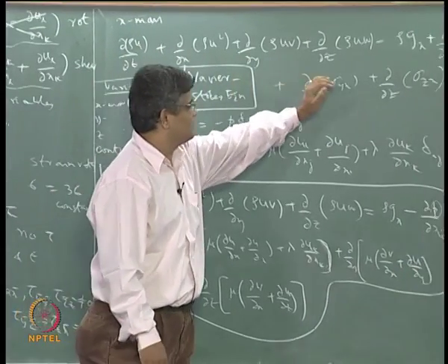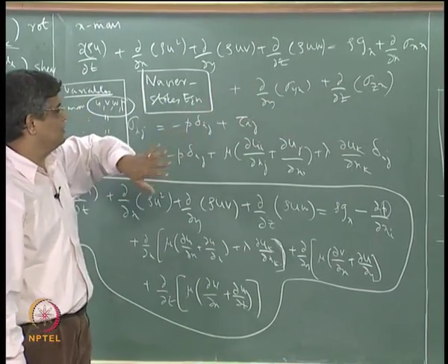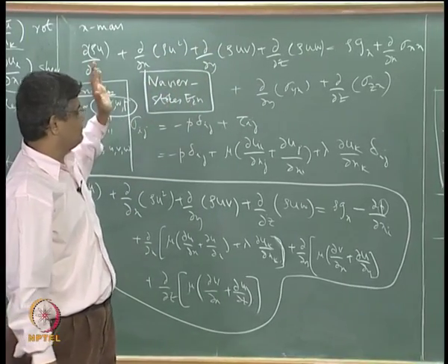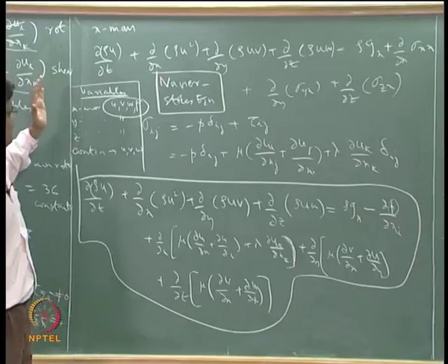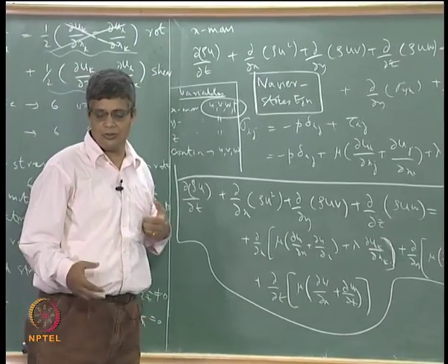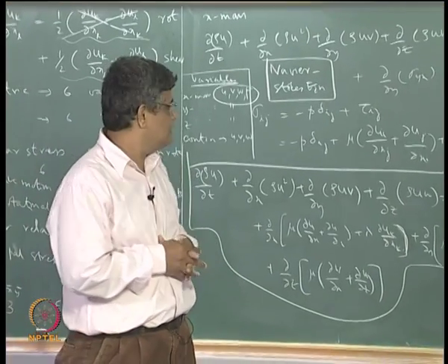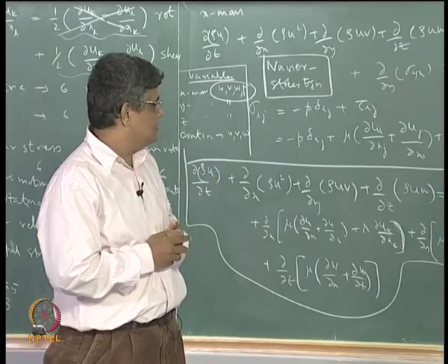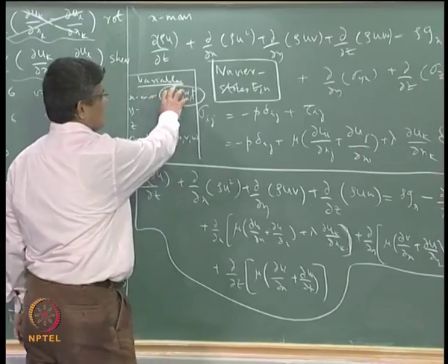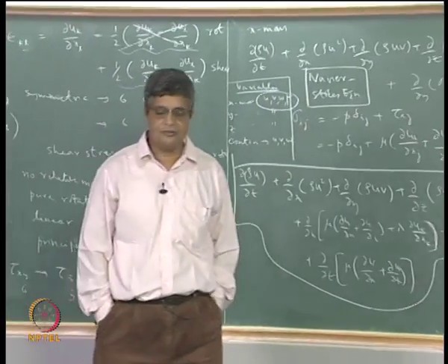So, if you have a description of the stress which is arising out of fluid motion in terms of the computed variables, then we can ultimately have a situation where we have an equal number of knowns and unknowns, and the problem becomes mathematically a closed problem. Okay. And for that kind of closed problem, for a Newtonian fluid, is the set of Navier-Stokes equations. Okay, so that is what we have for today.